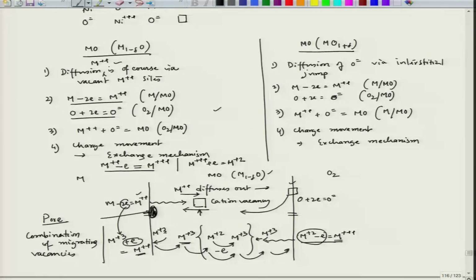Fine. So, there could be porosity formation on the metal oxide interface. So, this is the mechanism that could be possible in p type. Now, let us not continue any further from this. There is a great effect of this metal oxide structure, and that can decide how we alloy them, so that we can introduce resistance to oxidation.